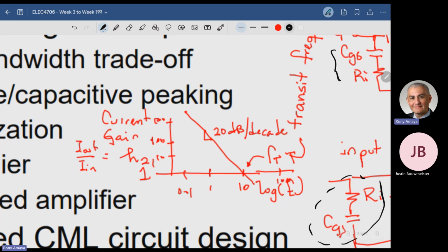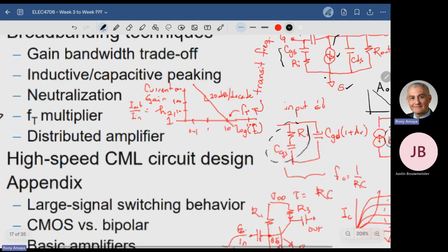It's intrinsic to the device. You cannot do anything about that. What we can do is control the geometries around it. We can shape the way that the source and drains are defined, how the gate comes in. And the moment we do that, we start to introduce our own personal touch into it. That now becomes a problem of the intrinsic versus the extrinsic, which again is a problem for Fmax, right?